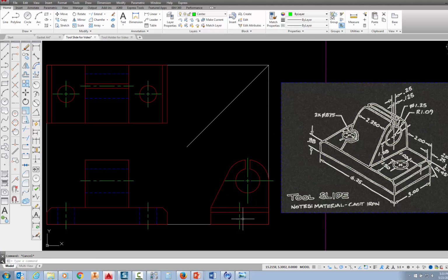And now all I need are those two hidden lines. Now I can project those hidden lines. First I would just go up here and go to the hidden layer, pick on that, pick the line command, and come right there where it's saying a midpoint, but I know that's actually my quadrant. And once it tells me that, I should be able to follow that across and pick, follow that straight down, pick and pick.